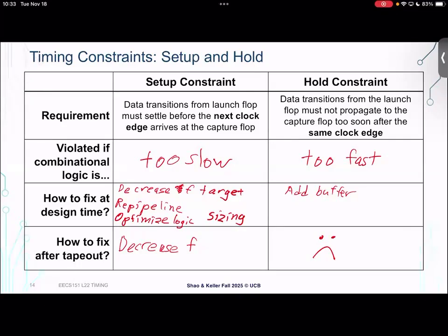Yeah, we're going to talk about exactly when you might want to fix these, but during physical design in particular is when you fix a lot of hold issues. So even though this hold constraint seems basic or trivial, right? You just need to make sure that there's a buffer or two between every flop. In practice, hold is a big headache because you really need to be very sure that you got it right. And so you tend to add a lot of margin, or you make sure that there's some hold slack in every path. You don't tighten it exactly in order to guarantee that.